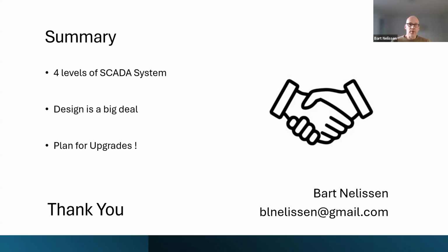And yes, I am available for companies interested in upgrading a SCADA system, and that being either a PLC or the SCADA interface. And replacing a PLC or replacing a SCADA interface does not require any changes to any of your process equipment. So your pumps, your valves, your level indicators, your transmitters, your switches, your floats, none of that would change. Those are currently wired into a PLC, and we would use that exact same wiring to disconnect from an old PLC and reconnect that to a new PLC, for example.